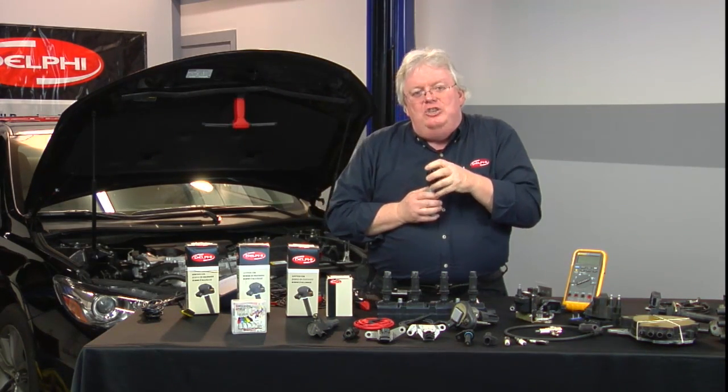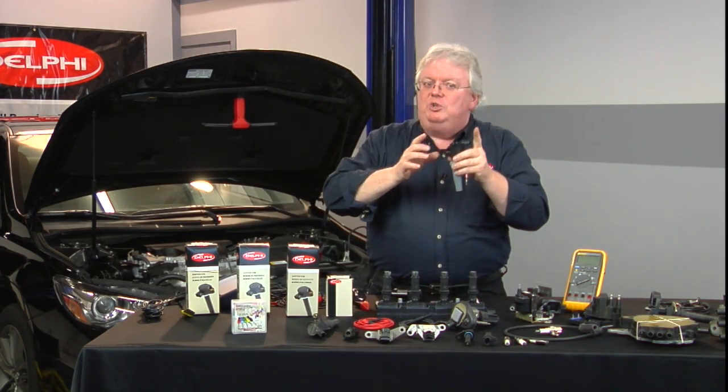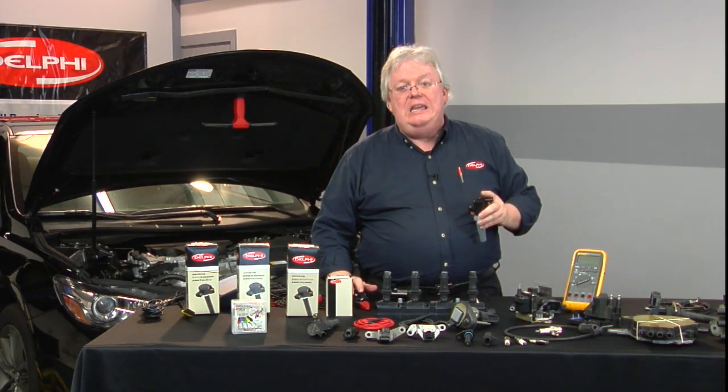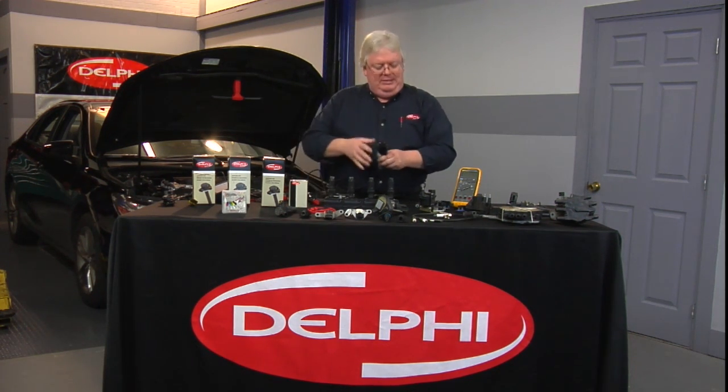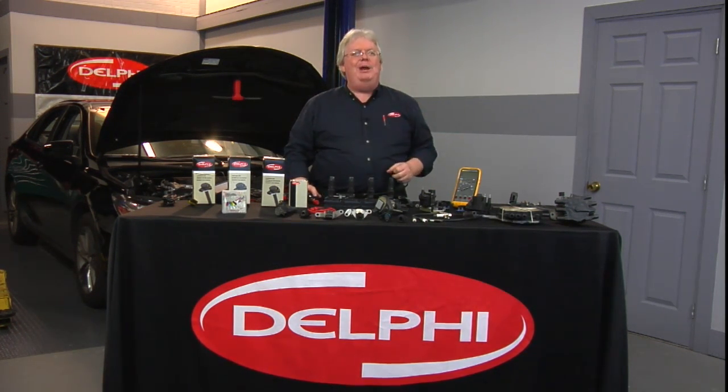That's not enough to fire that gap of air in that spark plug, but it's enough to make a sudden change of the coil next to the primary winding, which we don't see in this picture, but we do see here the secondary winding, which has 100 times more turns ratio. So we'll see several thousand ohms of resistance in the secondary winding. When it is exposed to a self-inductive kick on the primary, we have what's called mutual inductance, and that's where we see 200 or 300 volts become 20 to 30,000 volts. Step-up transformer theory 101. So most of you remember that, I hope, but just in case we need to brush up so we can move some of this theory into practical reality coming up right now.